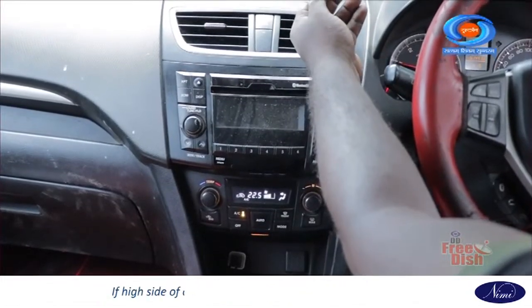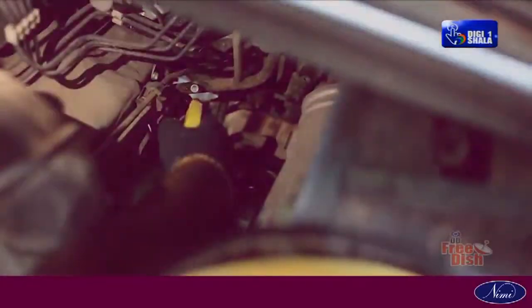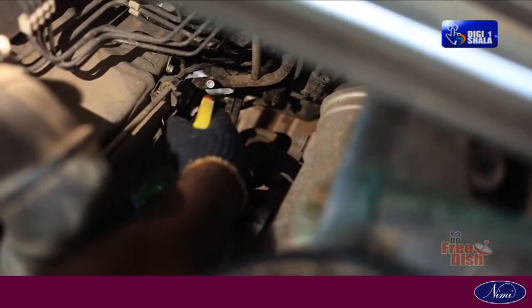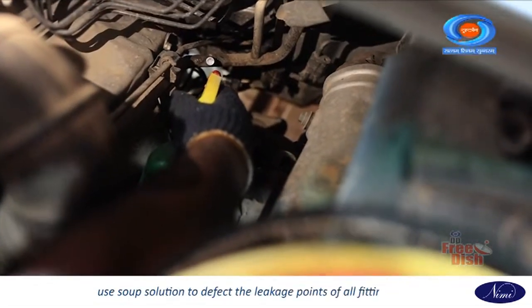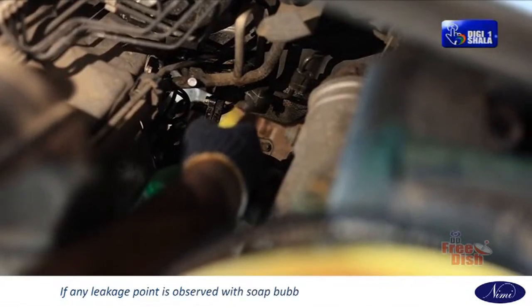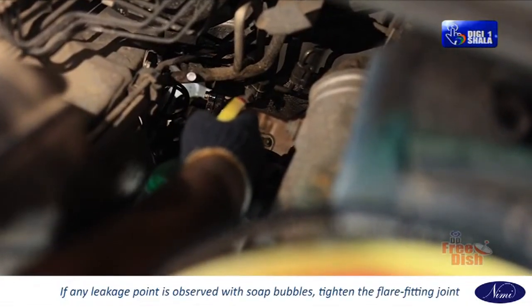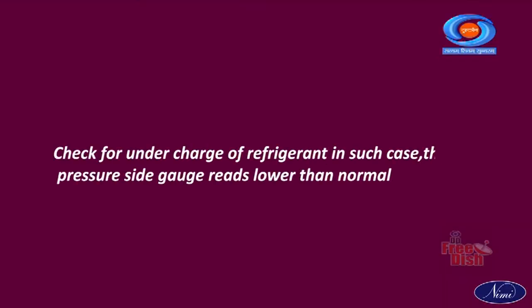If the high side of the car AC system is lower than normal, check for leakage of refrigerant. Use soap solution to detect the leakage points of all fitting joints. If any leakage point is observed with soap bubbles, tighten the flare fitting joint. If there is no leakage, check for undercharge of refrigerant. In such a case, the low pressure side gauge reads lower than normal.